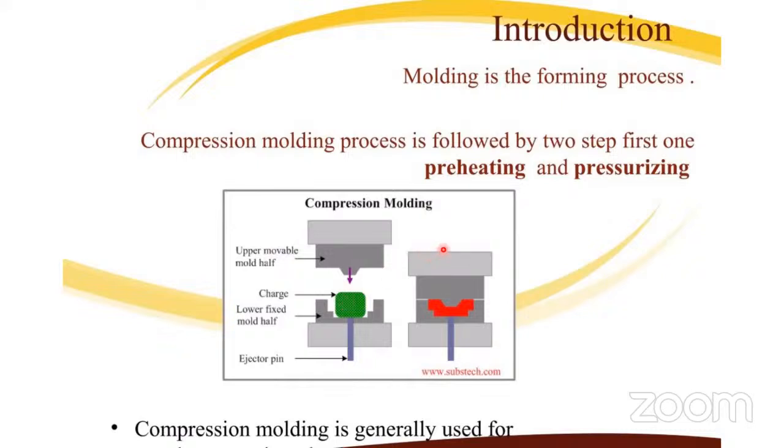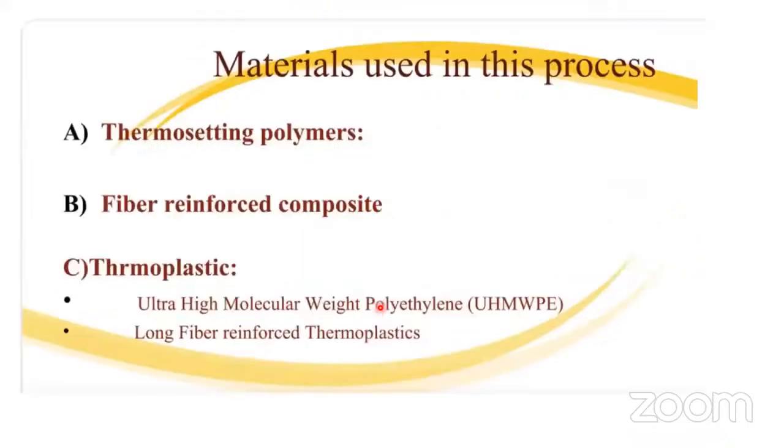Now after that, after closing this, see now, it's closed. So this is the ejector pin. Now this is a simple mold. After closing, you will get the article. Before this, if you see, this platen is heated. The mold has heaters here. You have to heat this first, both the upper and lower mold. So, friends, this is the simple principle of the compression molding process. We will go through everything now.